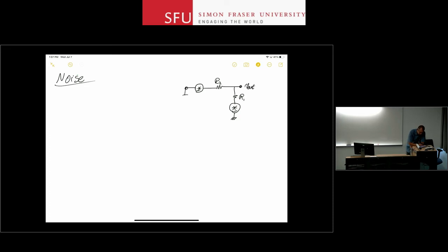So I can assume that V in is ground as well. So this is Vn1 and this is Vn2, and I know that Vn1 squared is 4 kBT R1, and Vn2 squared is 4 kBT R2. Okay?